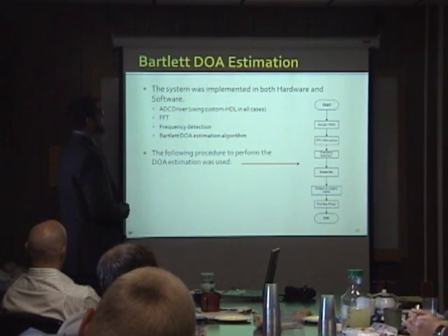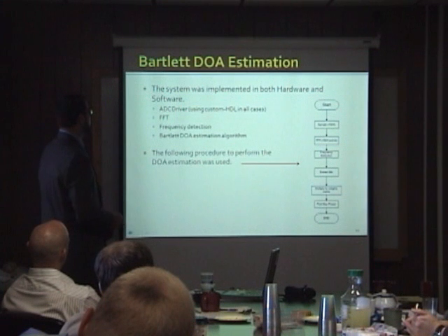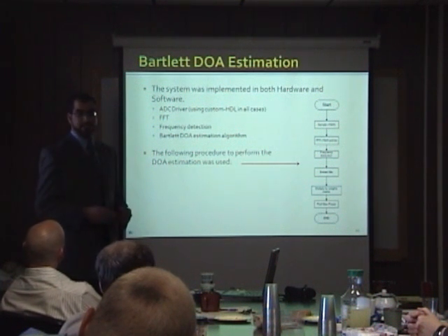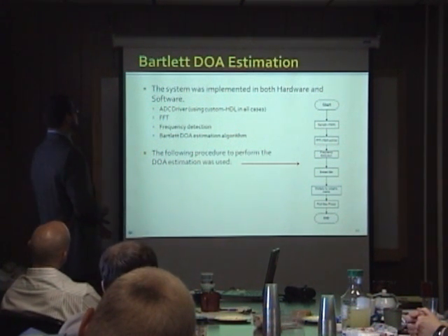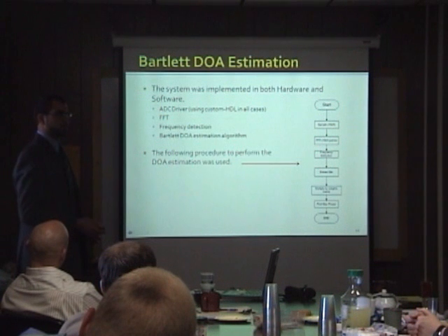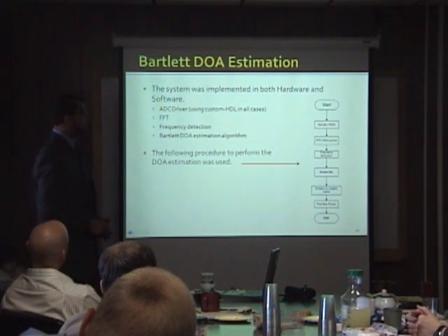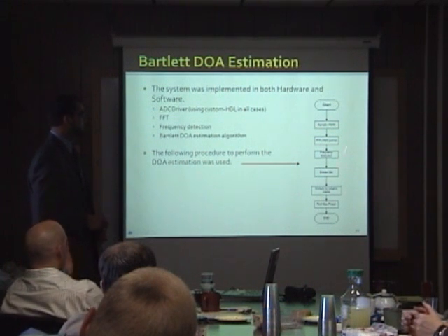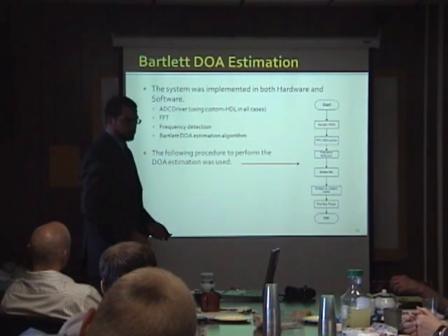The system was implemented in both hardware and software. It consists of the ADC driver, which, as mentioned, is part of the FPGA. It configures the ADC board and then receives the samples. Then the FFT module performs a fast Fourier transform on the sample data, and then we do frequency detection and perform the DOA estimation algorithm. That flowchart shows the functionality of the system.